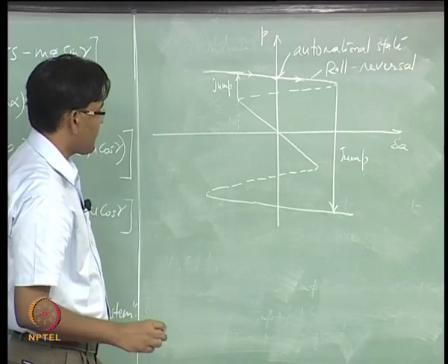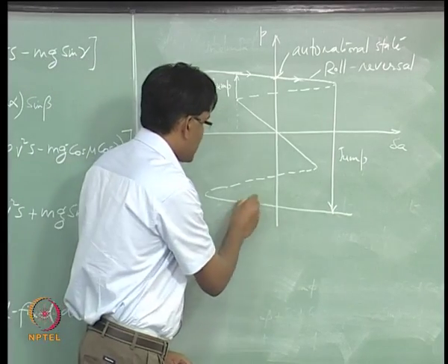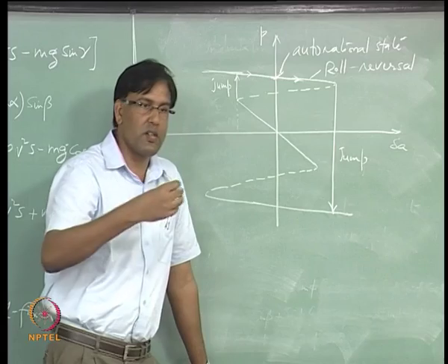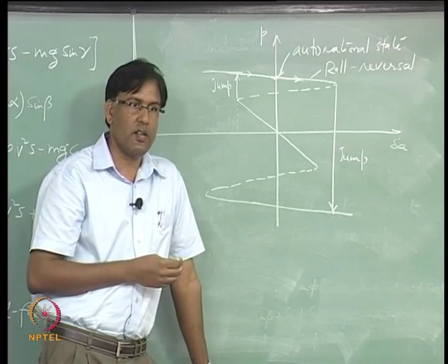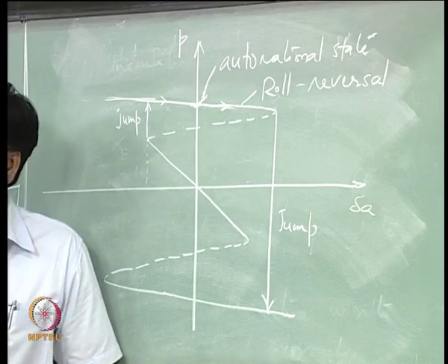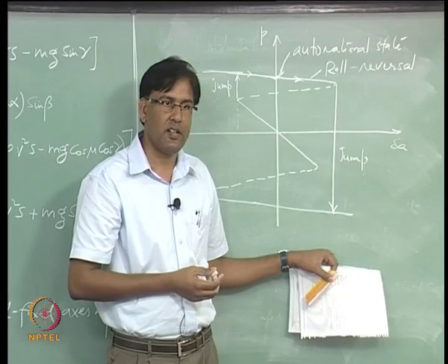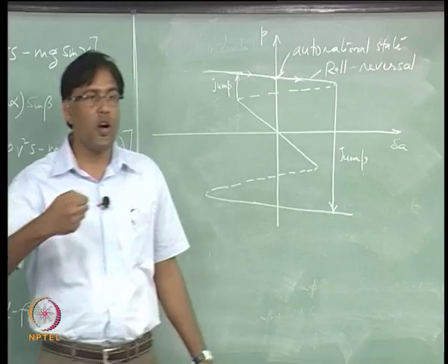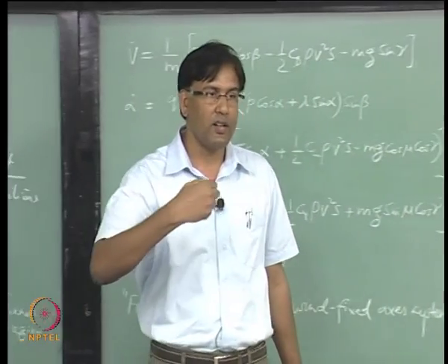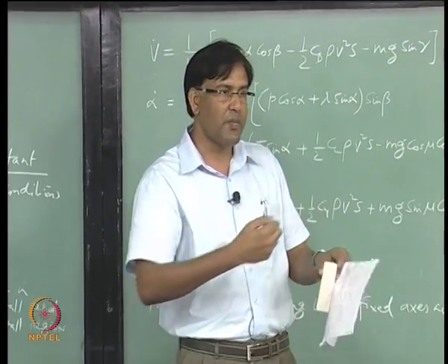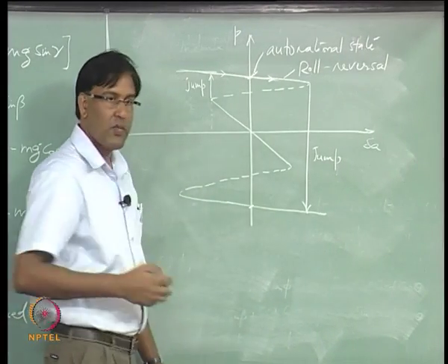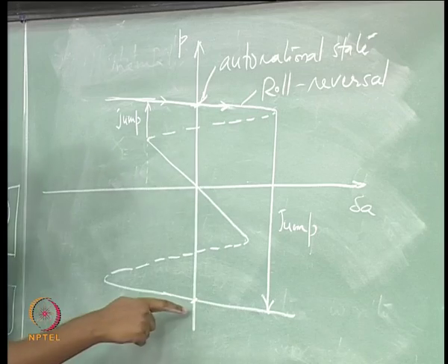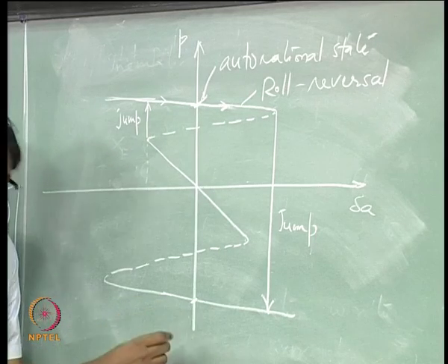All right. So, you have jumped here. Now, what do you want to do? What do you have? You have a negative roll rate. Now, you want to bring back your aileron and see what is happening. So, you start bringing back your aileron, and at this neutral condition, when the aileron deflection is 0, you see a negative roll rate.